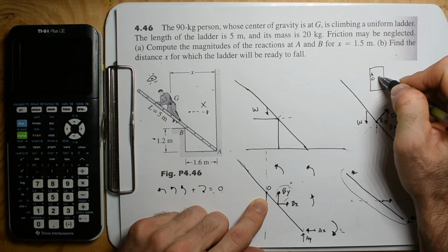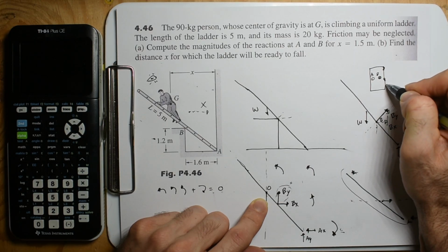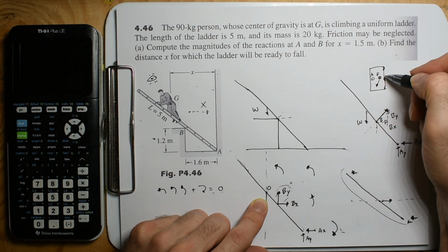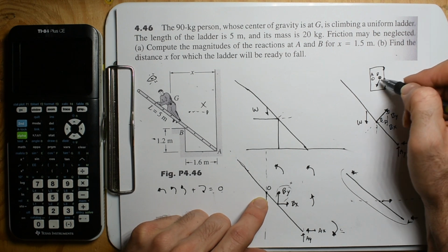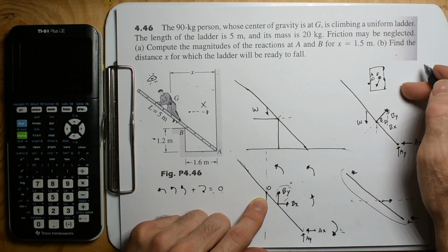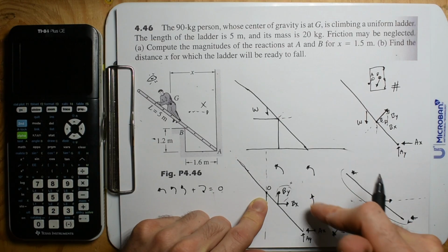Maybe we have a little nub sticking out, and you're going to try to open the door. Here's the hinges. You're going to try to open the door at point B. So you apply a big force, but it's still not very useful. You could apply a smaller force at A, and it could actually be more useful. So the usefulness is going to be the quantity of that moment.